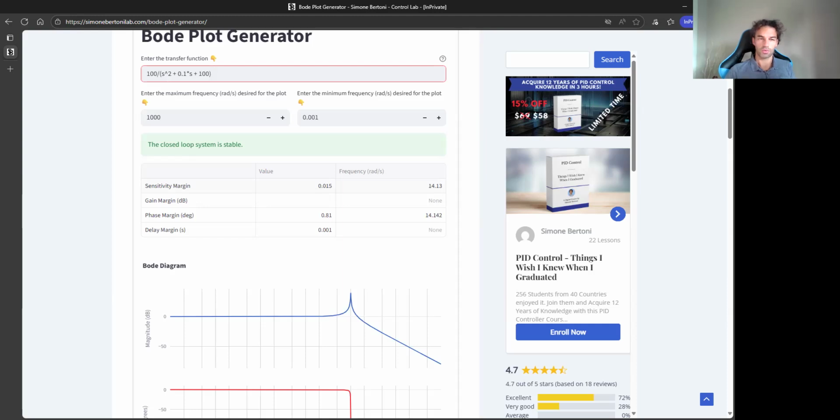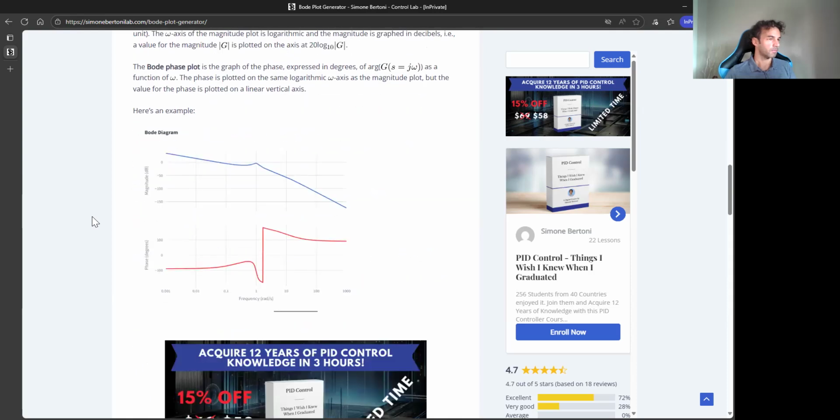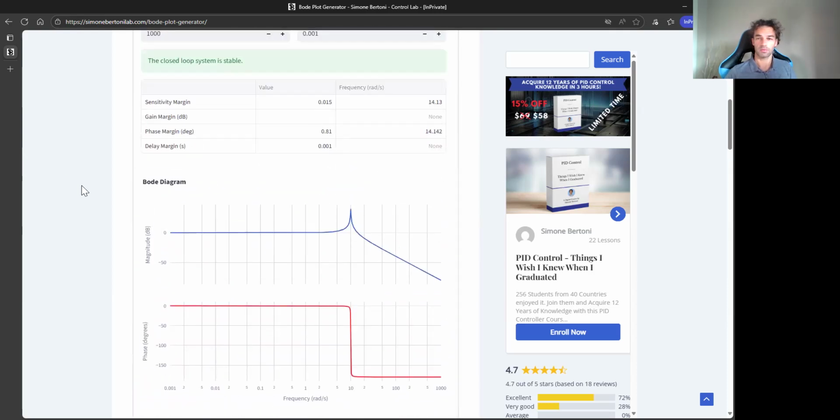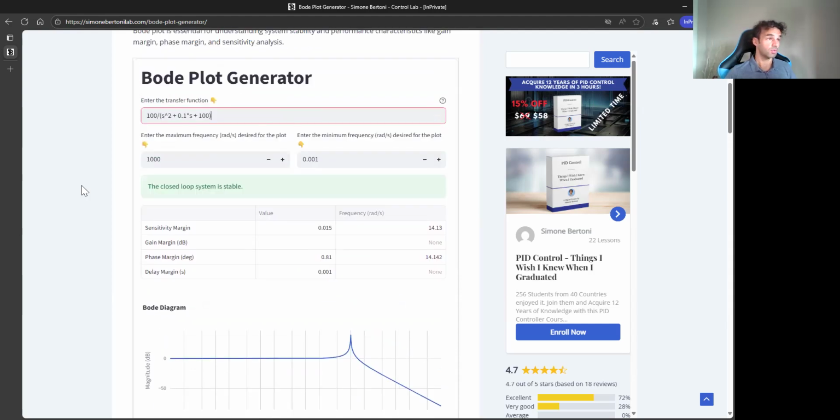We will call it G in this case. It's called G in all the explanation here. You can use that in the Bode diagram, and it's a simplified proxy to look at the Nyquist theorem, basically. So you can see if your closed loop is stable or not, and it will tell you.